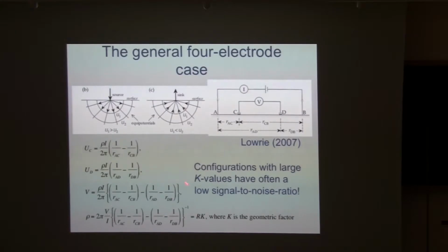And we can rewrite this a little bit as the resistivity being a voltage, what we measure with our instrument, a current, which we inject and also measure, and a geometrical factor that just relates to where we are measuring with respect to, so it's the geometrical information. Okay? So this is what happens, and it's the solution, let's say. You get directly your right electrical resistivity from one measurement.